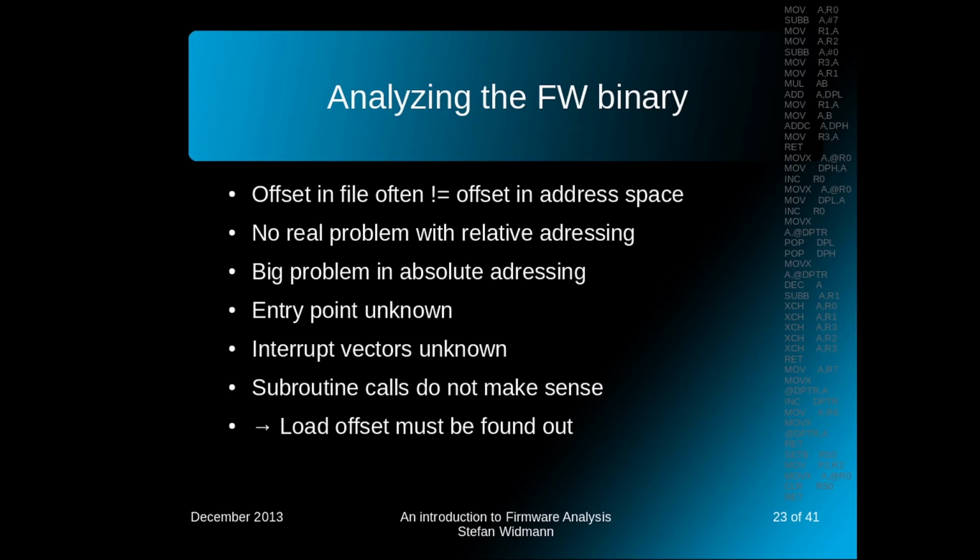We would not know where's the entry point, where should we start? Interrupt vectors might be decoded completely wrong. Subroutine calls do not make any sense. They go to outside of our firmware, for example, or in the middle of instructions. So the load offset has to be found out.